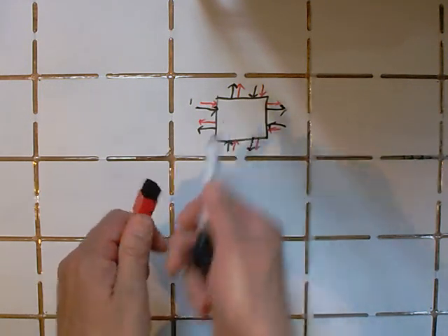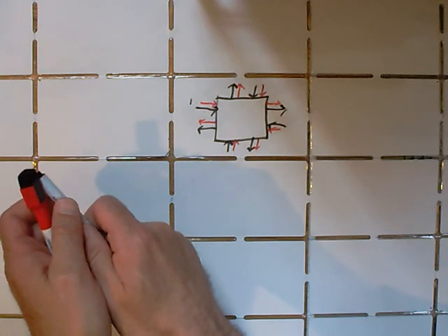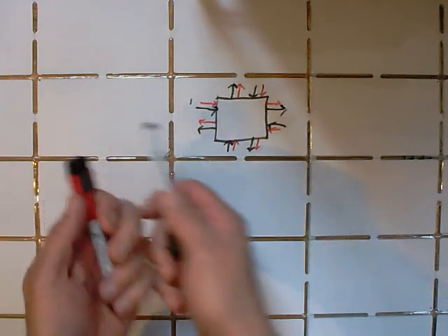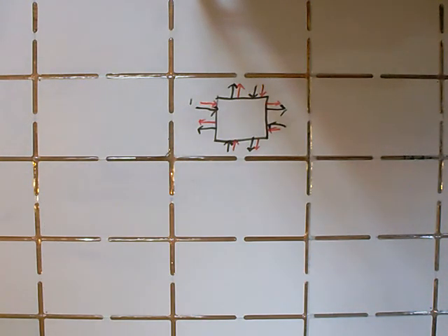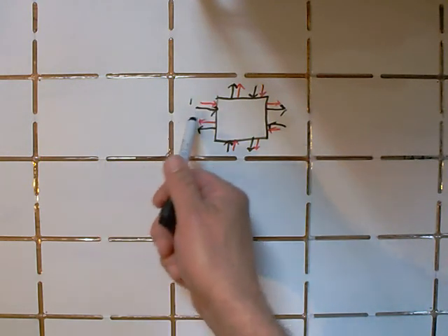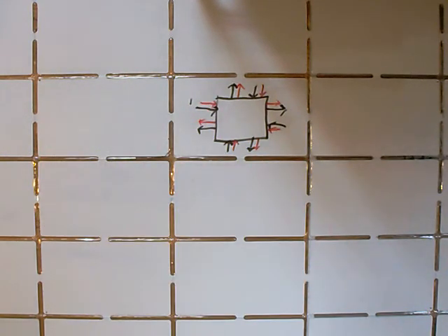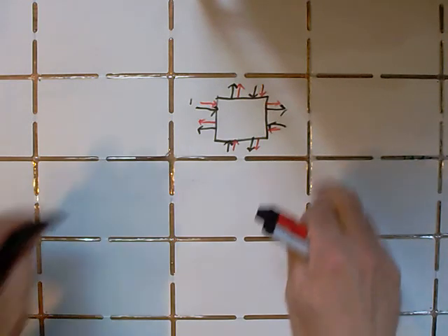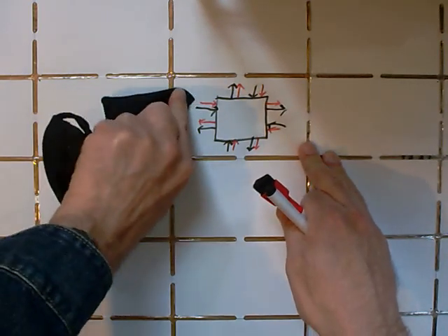So we can read the contents of a cell by putting a 1 into the C input and looking at the D output, and we can also populate the contents of a cell's lookup table by putting a 1 into the C input and supplying bits onto the D input. Now, how do we supply our bits? Well, there's a few ways.